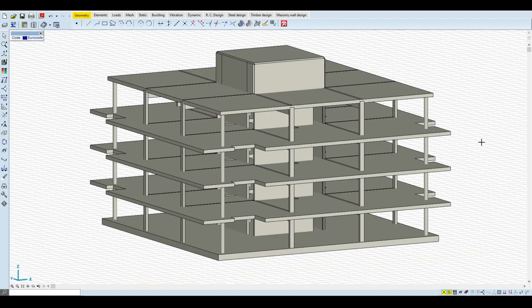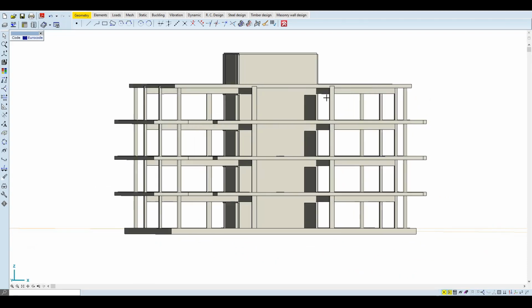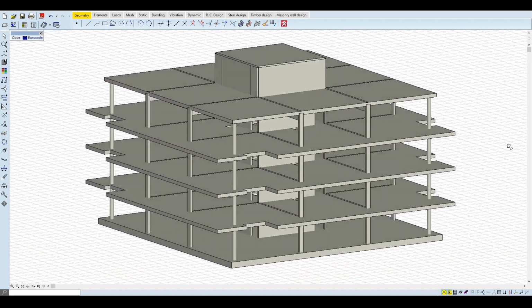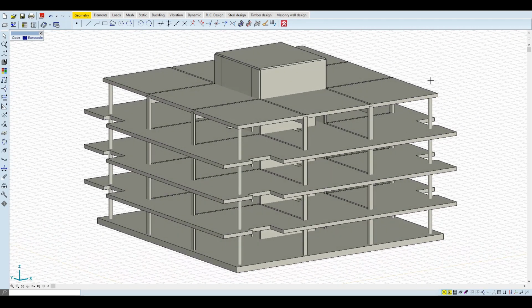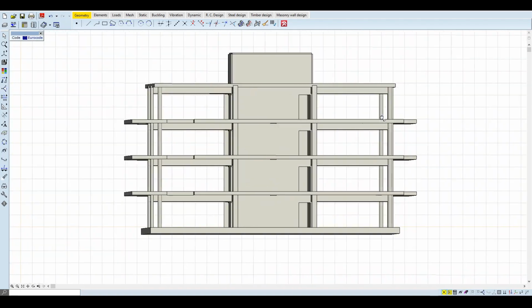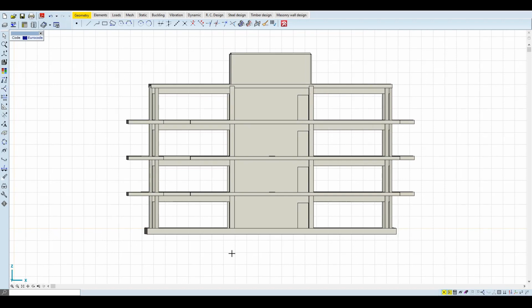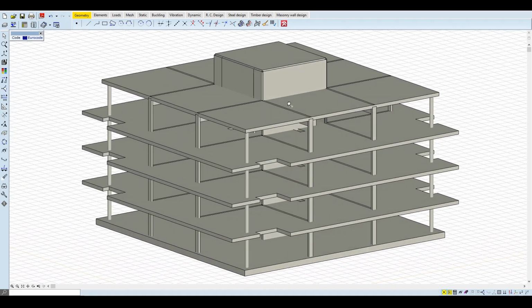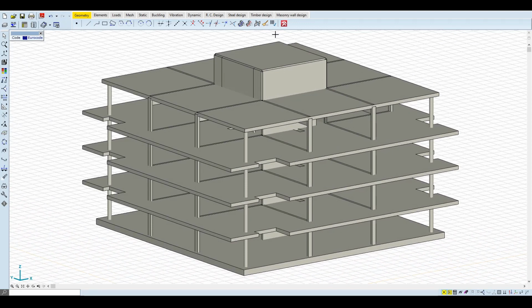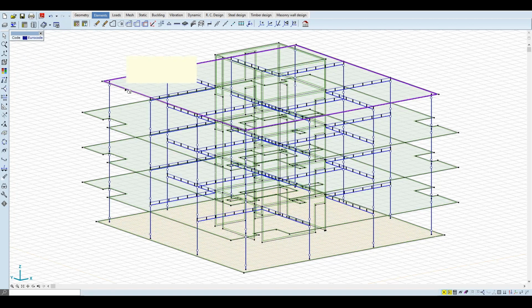The main beams are 20 x 80 rectangle profiles. We have circular columns with 35 cm diameter in the corners and rectangular 20 x 40 columns at the edges. The main load-bearing part of the structure is the core, with 20 cm thick walls and 6.8 meter x 6.8 meter outer dimensions. The concrete grade is C25/30. The reinforcement is S500B or C.